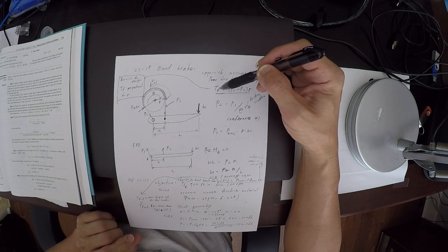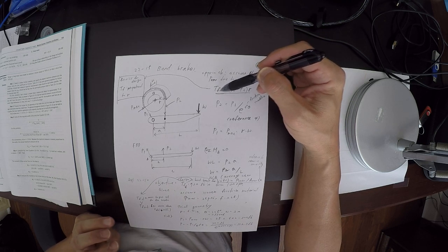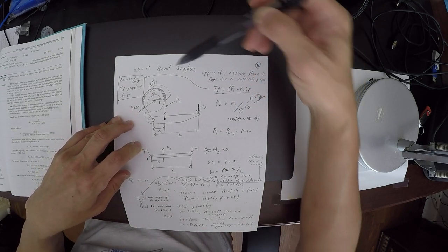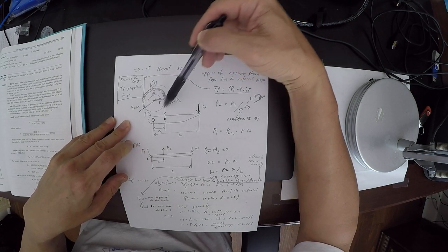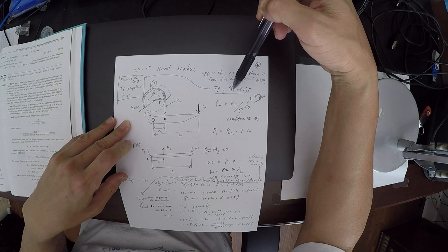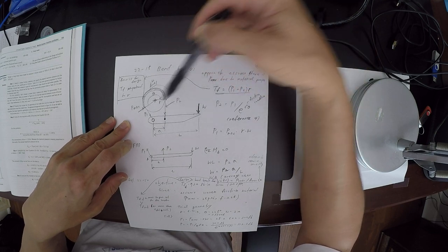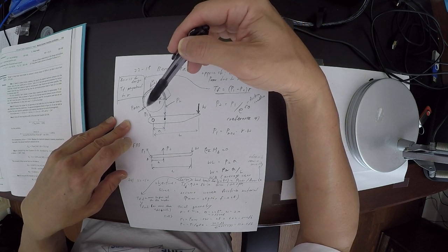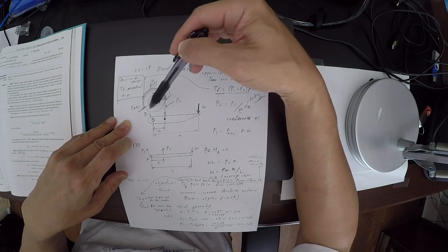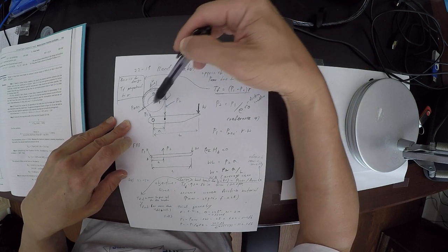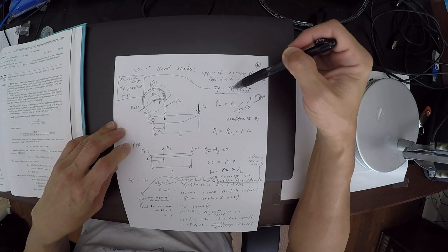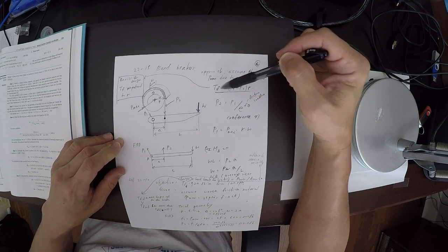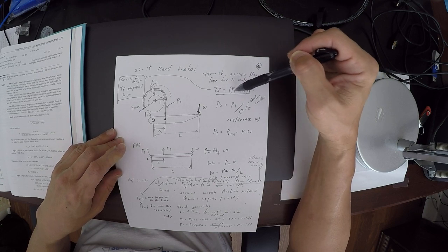The first one is the Tf, which is the torque you need to handle with the W. So torque has to be equivalent to, because there are two forces right here by the string, you need to subtract P2 from P1 times R. So basically we assume that the torque has to be equal to the difference of these two forces times the radius R. Okay, maybe this is not exactly the physical solution for torque, but it is an estimation of the torque, which is proportional. The Tf is proportional to P1 and P2.